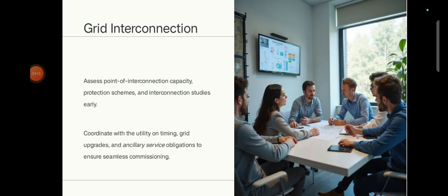Grid interconnection. Assess points of interconnection, capacity, protection schemes, and interconnection studies early. Coordinate with the utility on timing, grid upgrades, and ancillary services to ensure seamless commissioning.